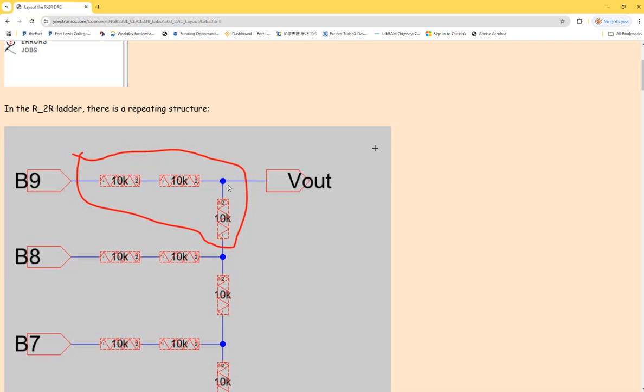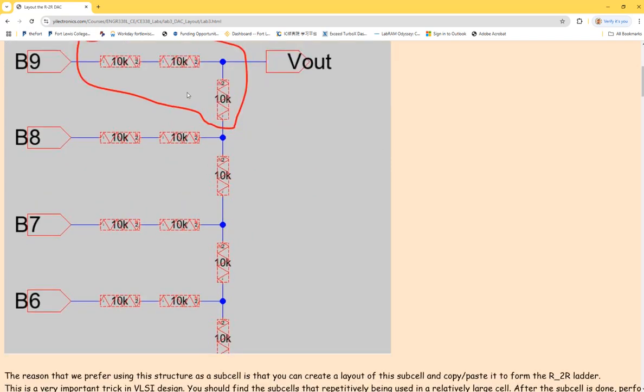What are the benefits of doing this? Yeah, that's great. And also for error checking. Imagine that if you have 20 resistors, it's fine. You do a DRC check, boom, you see like 5 errors. Not a big deal, just find those errors and check them. What if you have a billion resistors? You want to manually lay out every single resistor, and you do a DRC check, and it shows you like 1 million errors. What's the next step? Locate every single error and fix it manually?